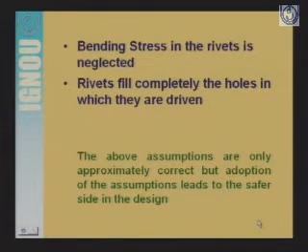Next assumption is that bending stress in the rivets is neglected. Here it is a very important assumption that we are neglecting the bending stresses in the rivets. Next assumption is rivets fill completely the holes in which they are driven.